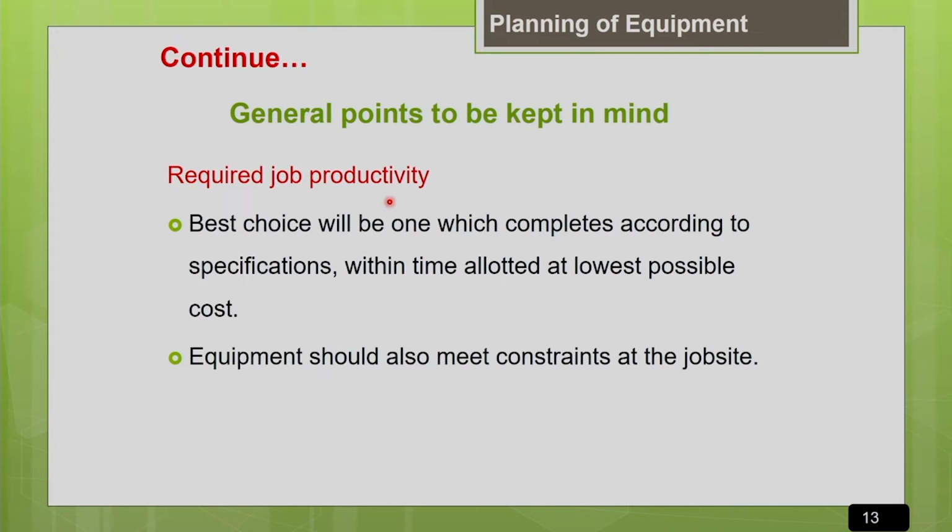The job site may be in a very remote place, so accessibility of the machine to the site may be very critical. Your job site may be at a very high altitude, the temperature may be very aggressive, it may be a very cold place. All these conditions will affect your equipment selection, and should be taken into account apart from the economics of your project.